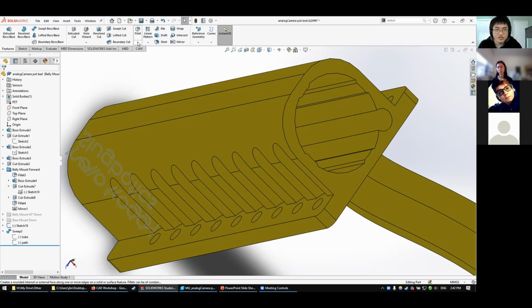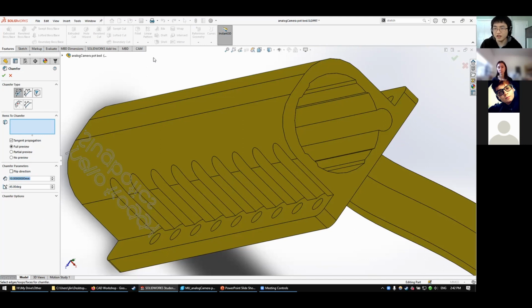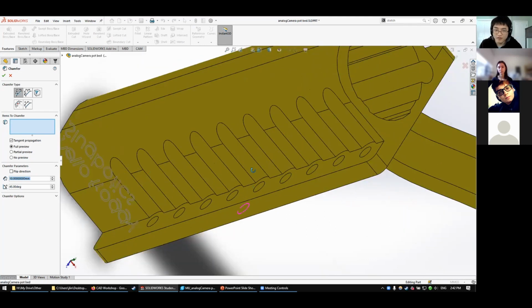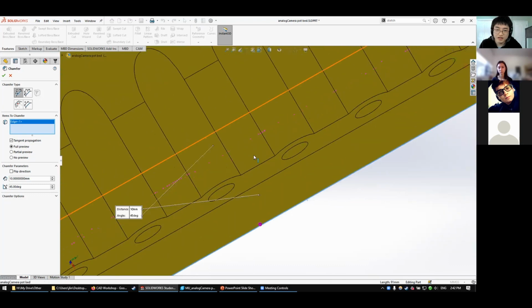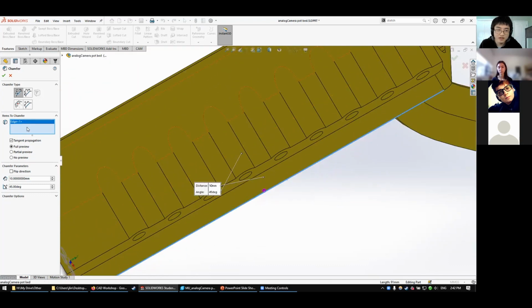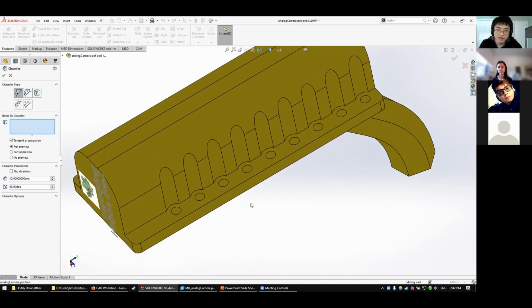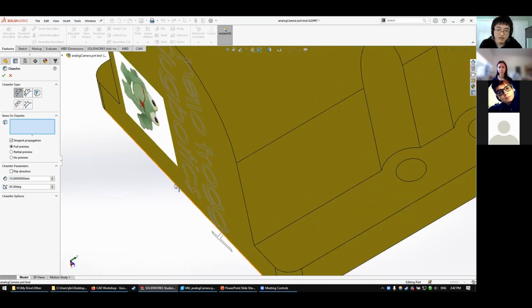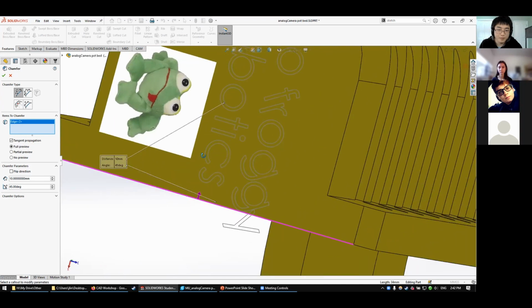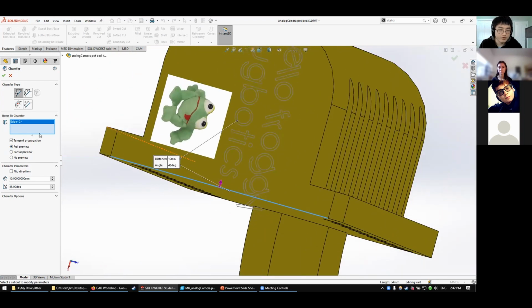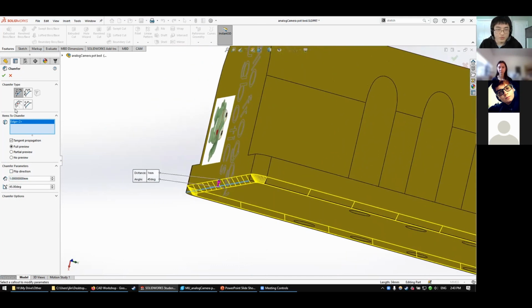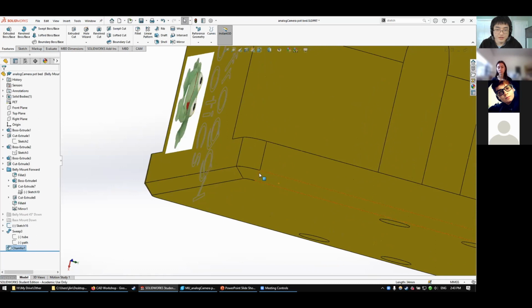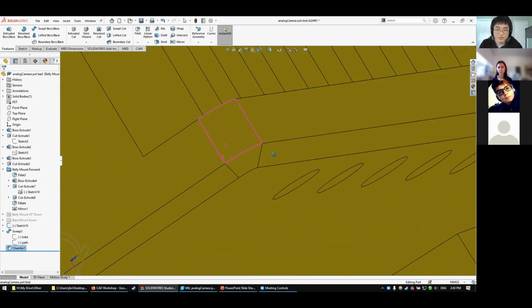You can also make chamfers. A chamfer is just like making a straight cut along the corner or edge. So if I make a chamfer along this, it's not showing me a preview because by default it assumes you want a 10mm chamfer. So I'm asking for a full preview. I want a 1mm chamfer, and then it will trim the edges. So now I have a flat cut along all the edges along the bottom base.